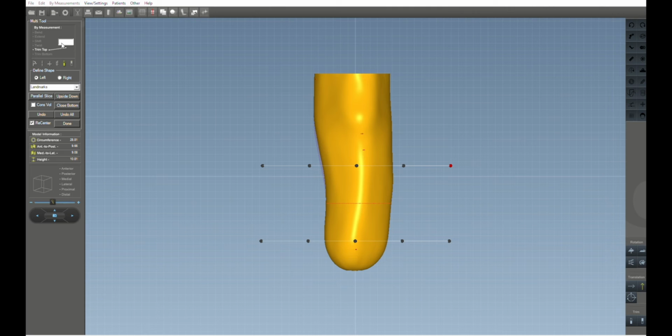We can also go over here, say I want 1 centimeter, go to extend, and because I've selected the point on the plane right over here, it's going to apply it right there. I click extend and it'll give me exactly 1 centimeter of extension. Okay, so that would be the extend, and then I could of course hold down the left button. I could shorten the model, or they're reversed at the same time.